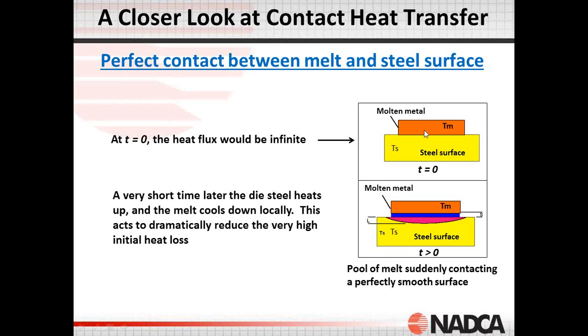So in this condition, at time 0, in a perfect world, if we have liquid material suddenly touching a steel surface in which the surface is ideal, there's no contamination on the surface, the initial rate of heat transfer at time 0, the very moment it contacts that surface, the heat flux, would be infinite.